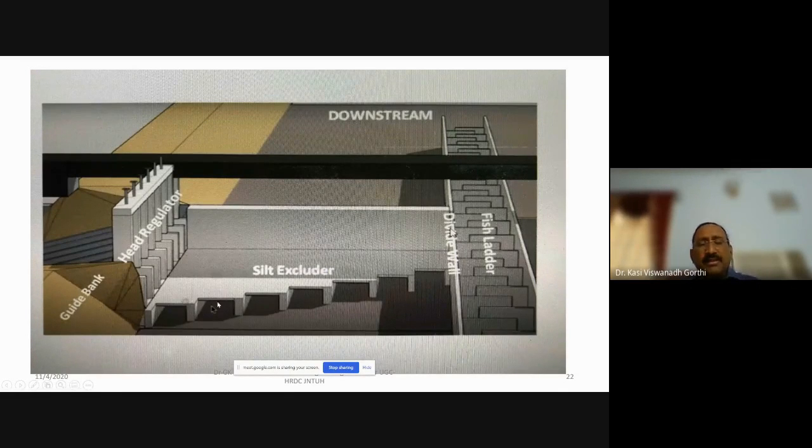And as it is moving, the length of this tunnel also is getting reduced. These are all the tunnels which are provided like rectangular boxes. This total constitutes a silt excluder. Horizontally, the water may be having two sheets: a sheet of water relatively clear with less silt content, and the bottom sheet of water having more silt content.